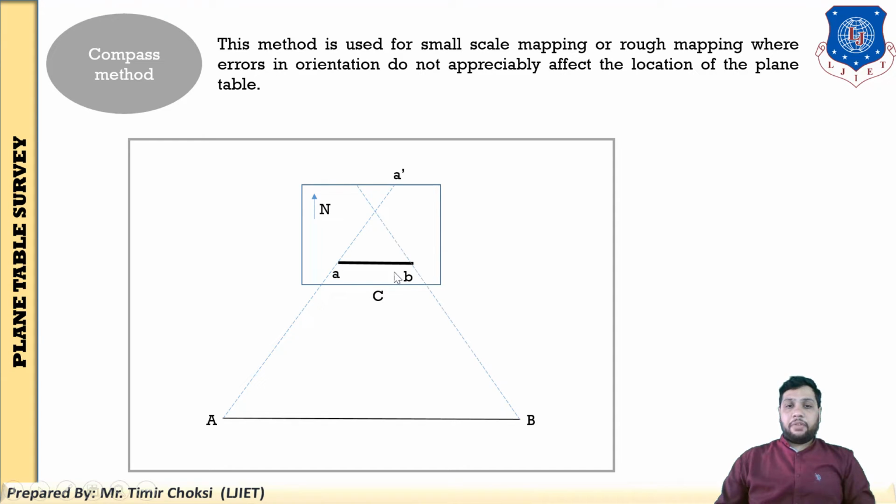Similarly, pivoting the alidade at B, draw the ray, it is B dash. The intersection of lines A dash and B dash is your completely new station established on the drawing sheet, not on the ground. It is the small c point. Then clearly listen, students, the last step: you transfer the point C to the ground using the U-fork with plumb bob.